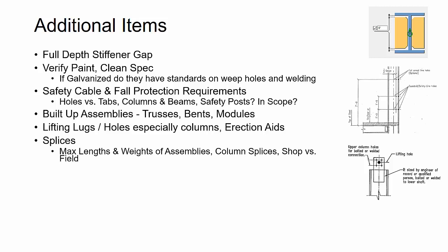And then again, looking at splices, shop splices versus field splices. If you have columns that are more than 2 or 3 stories high, the length of the assembly starts to come into consideration of what you can load on the truck, as well as decking out in the field.